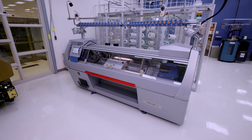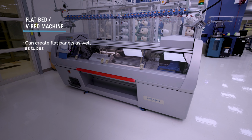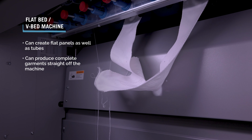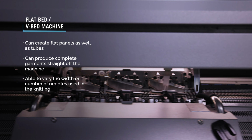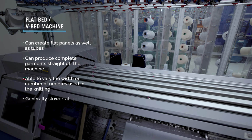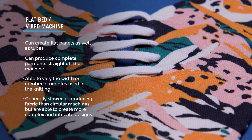Another type of machine that can be used to produce weft knits is the flat or V-bed machine. This machine can create flat panels as well as tubes and can even produce complete garments straight off the machine. Flat machines are able to vary the width of the knitting by selecting the number of needles used and to change this number throughout a piece. Flatbed machines are generally slower at producing fabric than circular machines, but are able to create more complex and intricate designs.